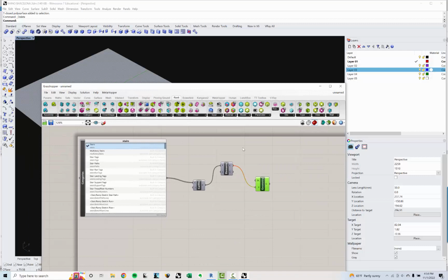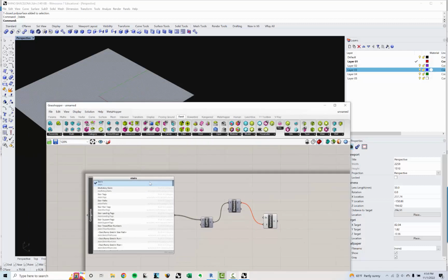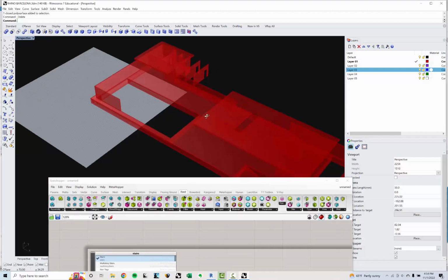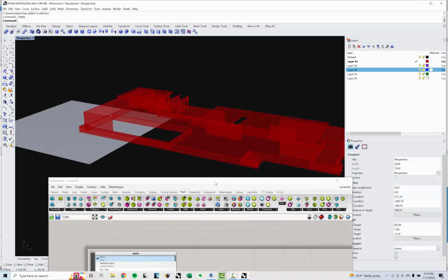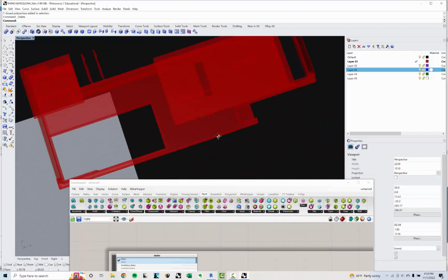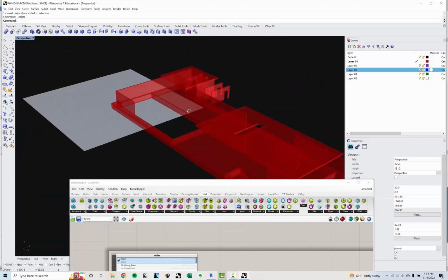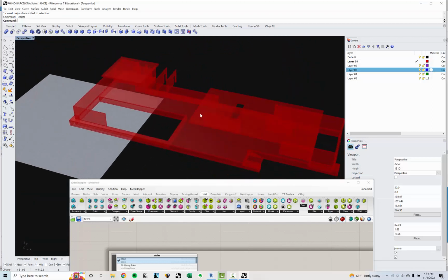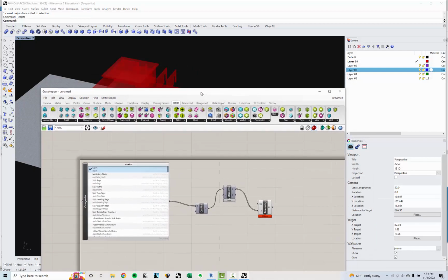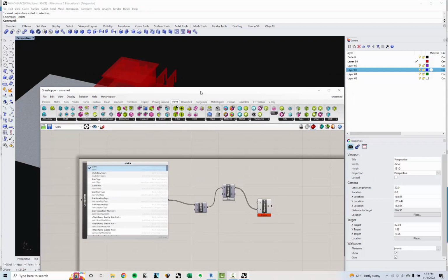And this again can sometimes be a little bit finicky. So you may need to just recompute and then it'll pop up. But sometimes when you've just sort of undone things and edited geometry, you might just need to recompute. So now I've got this in here that I can then start to model against and use as a reference without having to bring all that geometry in. So that's like a real basic, simple definition of how you would bring geometry from Revit into Rhino.